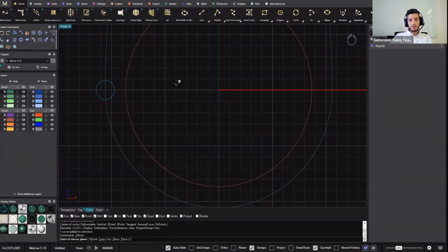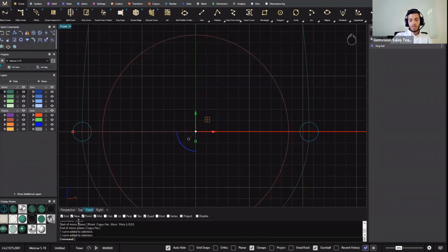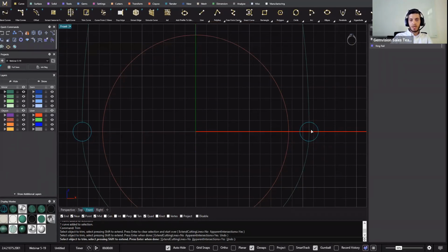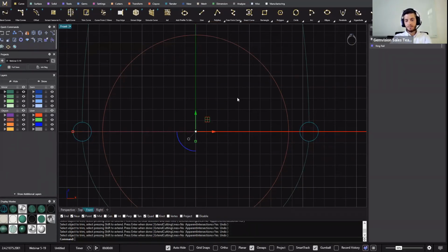And then I want to mirror to the other side. Again, hold shift and go straight up and get it to the other side. Now with these selected, I can trim one more time and trim the insides of these. Whenever you're done, you can just delete them.